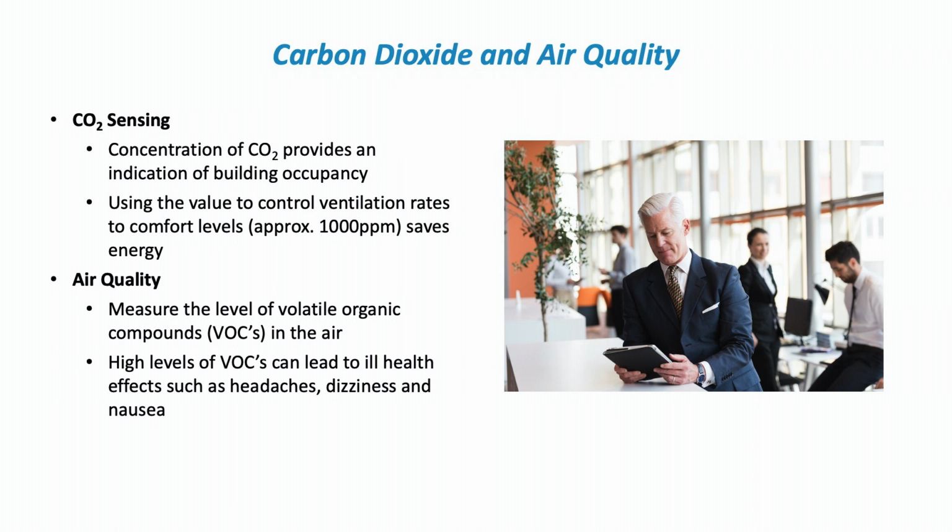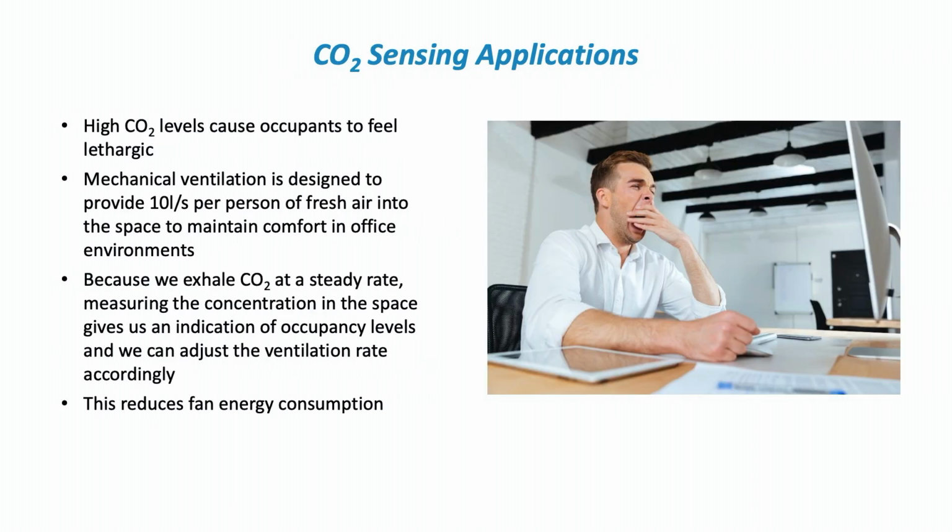These VOCs tend to not lead too much to ill health, but they can cause headaches and dizziness. But we do need to treat air quality and CO2 sensing in a slightly different way. So the CO2 sensing, the reason that we control it is obviously for the comfort of the occupants. People need approximately 10 litres per second per person of fresh air in an office environment. That's how much air we have to bring in. That's the CIBSE recommended requirement. Because we exhale CO2 at a steady rate, so we all breathe in oxygen, we breathe out CO2.